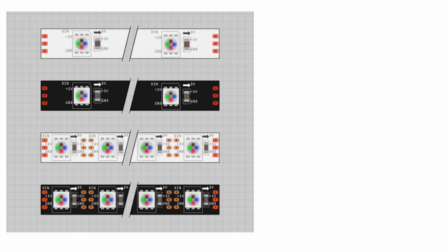And I already mentioned the strips. There's the strips. You buy those from our friends in China for a couple of pounds and you cut them to length. As you can see, looking at the bottom one there, you can see the connectors and where you snip between them. And every time you snip between them, it doesn't affect. You don't have to worry about addresses or any of that stuff. These things are non-addressable. And I'll explain that when I get into working out how they work in about 3 slides from now.